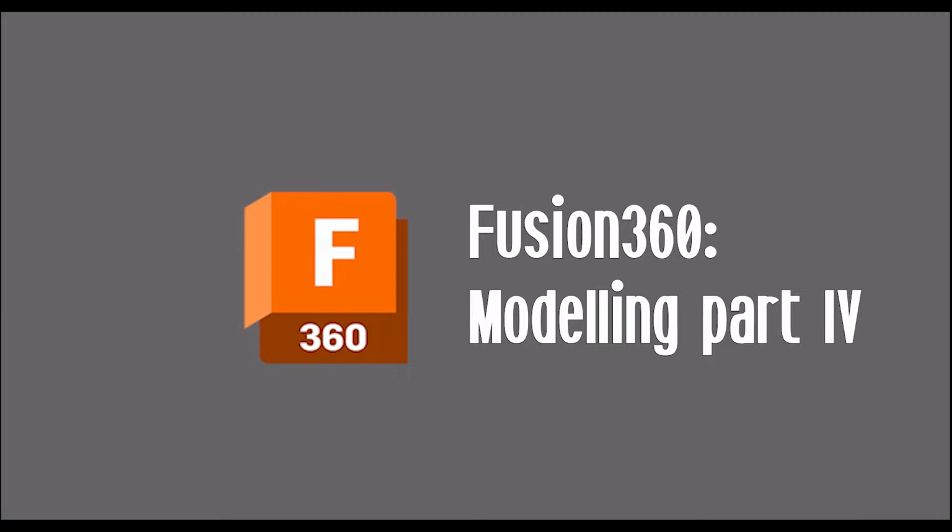Specifically we're going to look at combining the draw tools to make complex shapes. We're going to look at the offset plane again and using the revolve tool to sculpt a complex shape as well. There's a lot to learn, so let's get right into it.